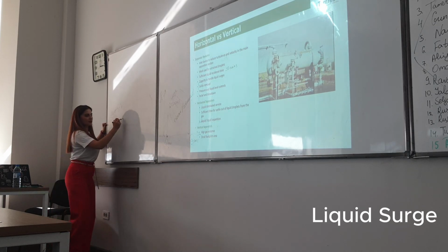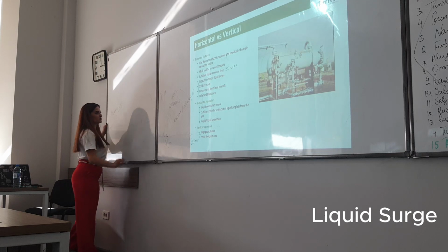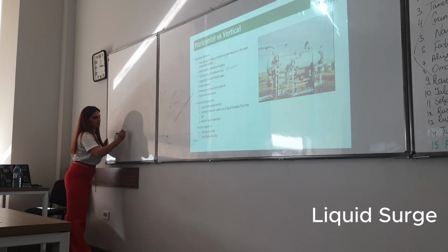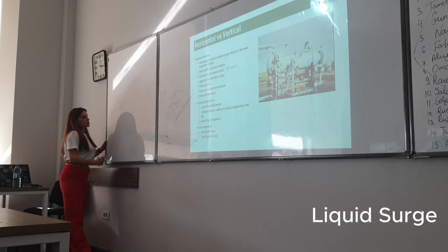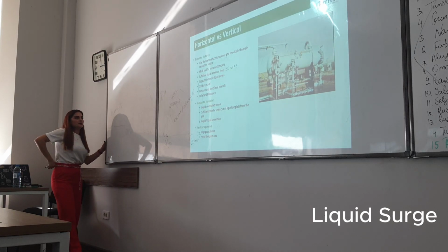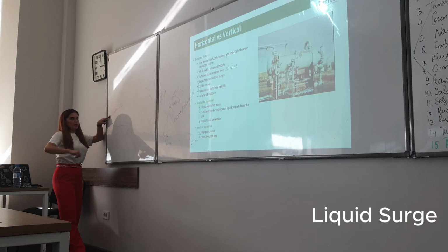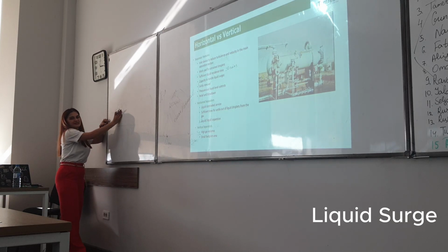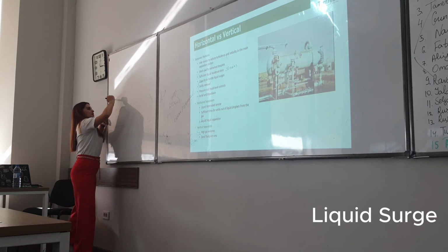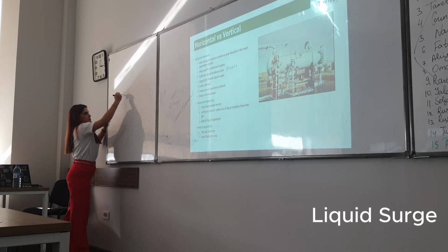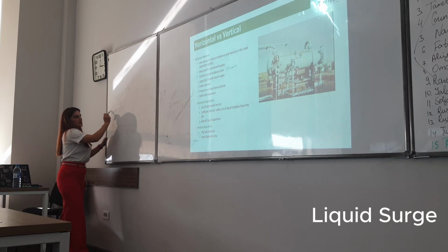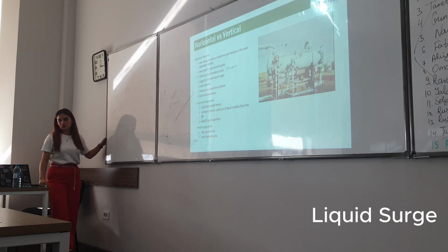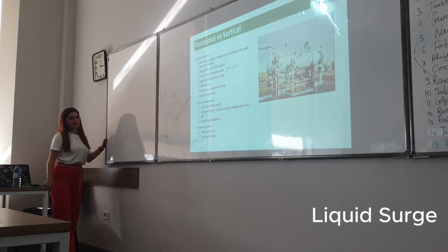This is also a continuous process, and in the continuous process you get the water here, the oil from here, and the gas, right? Suddenly something happens, and your 20,000 kilograms per hour, which we set as the set point, suddenly increases to, let's say, 50,000. As we increase the flow rate, it will definitely affect the steadiness of the flow. Why do we need steadiness in the separation?